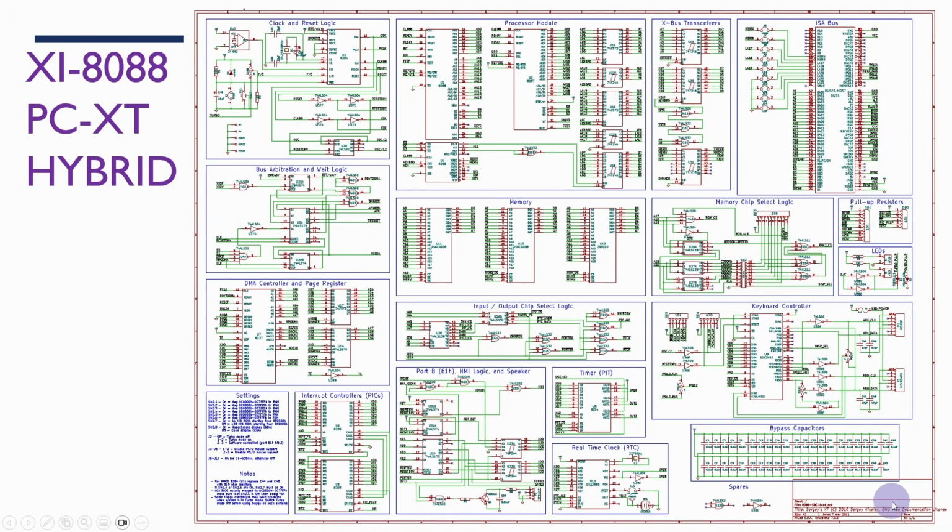So in addition to the original PC and the PC-XT, I've also analysed the XI8088. So this was a hybrid design that Sergei Kiselev produced, and there is a PCB version of this. And this design was using static RAM, so no dynamic RAM refresh, which is recommended for any sort of breadboard PC. You don't want to be messing around with dynamic RAM.